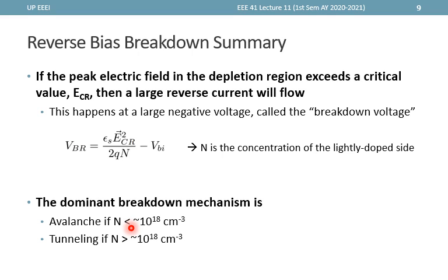A bit of information: we call the diodes Zener diodes because people back then assumed that only tunneling occurs and did not consider avalanche breakdown. However, not all Zener diodes break down through Zener breakdown. Some of them actually break down via the avalanche breakdown mechanism.